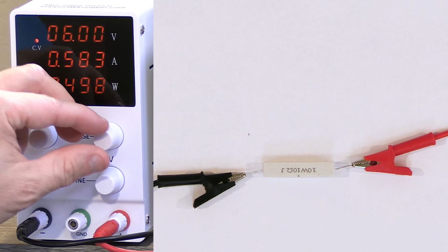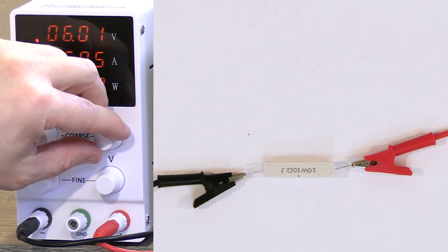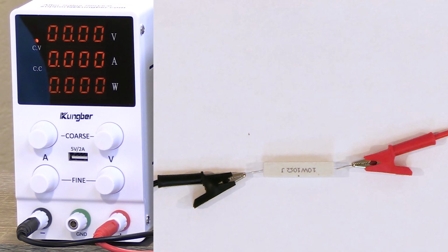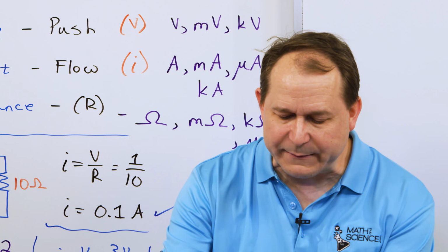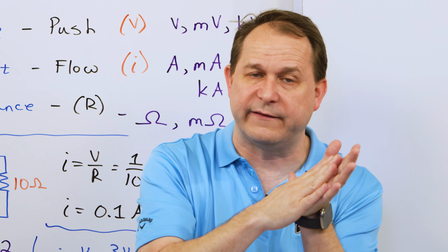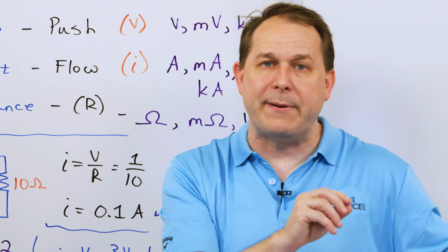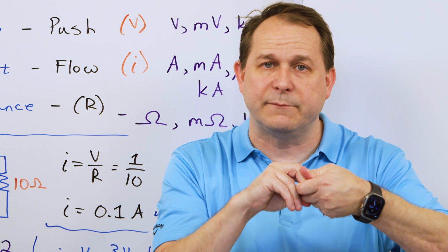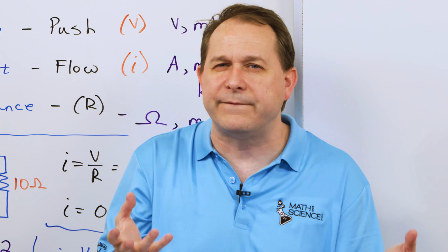Now you have to ask yourself, oh, why is it different? What's wrong with that? What am I doing wrong? Well, this wire is not a perfect resistor, right? So this is the difference between theory and reality. It's not a perfect conductor. This wire, even though it's made of copper, actually has a very small resistance. Also, notice I'm connecting these things with these alligator clips, so there's a little contact resistance where they connect, and also, you can't see it off the camera, but I have another connection point from the power supply to these wires. There's another contact point. The higher and higher I go with the voltage, these little imperfections are going to be magnified a little more.